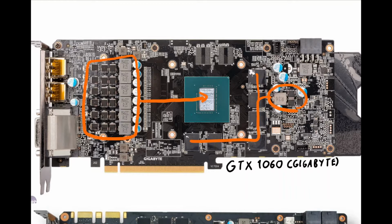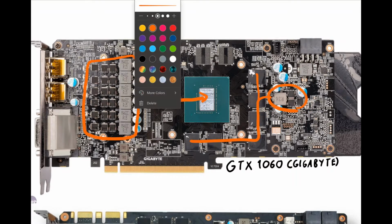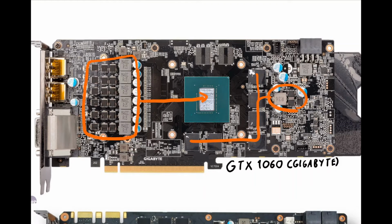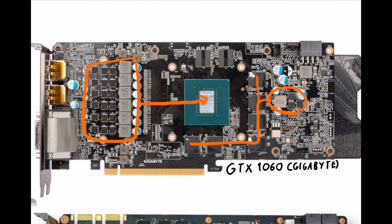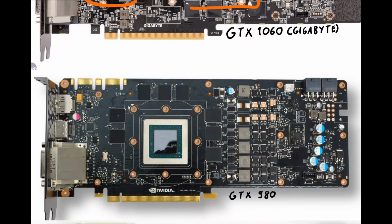There are slight differences for having it on the left side, because your power basically has to travel all the way from the connector over there and then back into the core, which is on paper slightly worse than going through there and then into the core. But it's not really a measurable difference. So yeah, vCore can be on this side, but you can see here again vMem here, vCore over here.